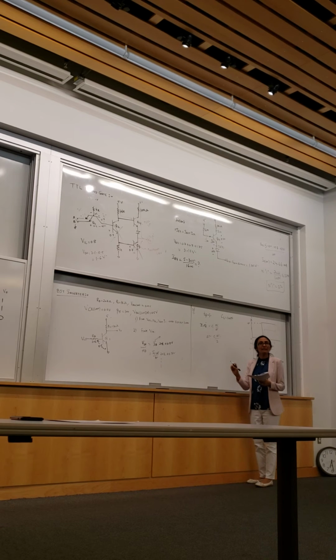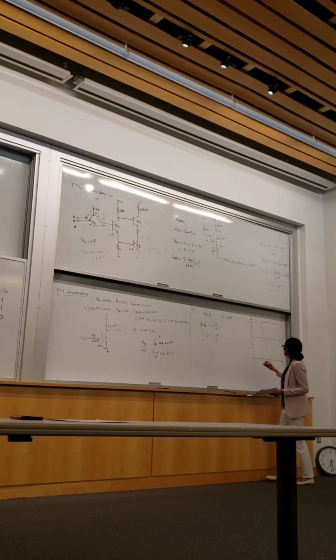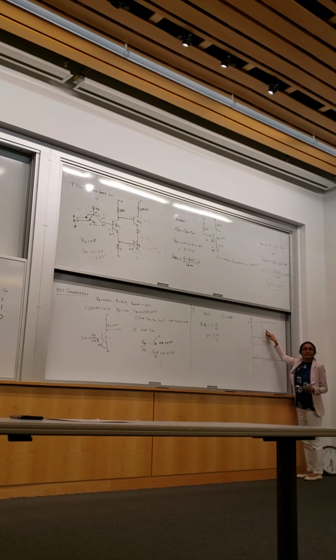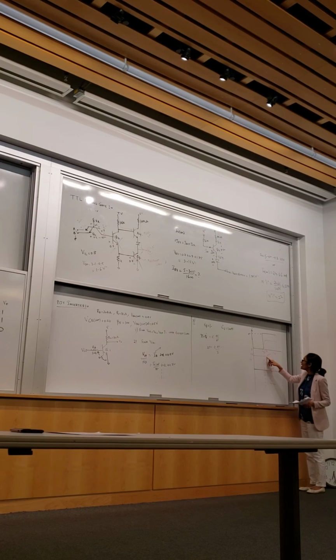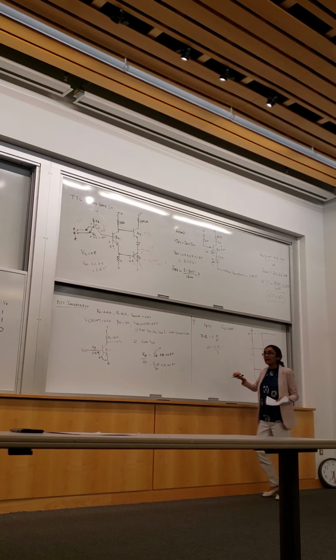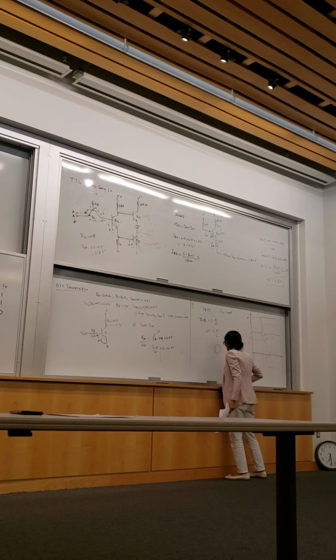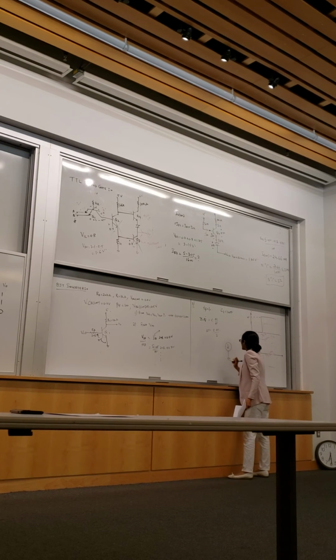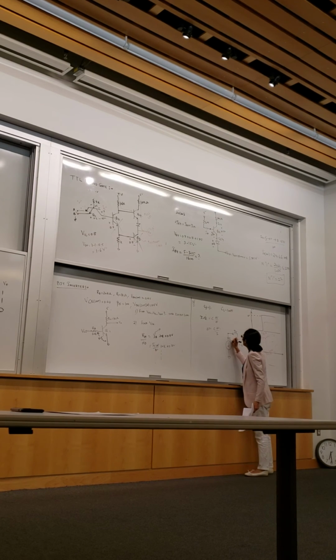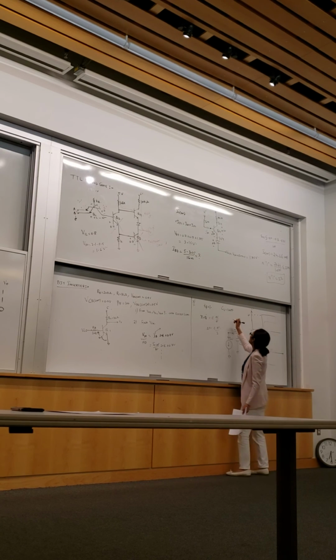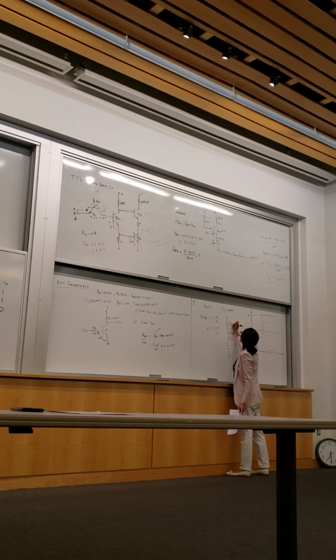What I'm going to do is draw the model and write down the equations. For the fall time, the base emitter voltage is positive 0.7. What about the base collector voltage? In this specific interval, the collector voltage is decreasing, so the base collector junction is most of the time reverse biased. Base emitter is forward, base collector is reverse biased. So we can model the transistor for this case as a current source. I'm going to replace this transistor with a current source. And I have a load capacitance here, CL. This is my I0 and this is my IC1. And right here I have a 1 k ohm resistor.